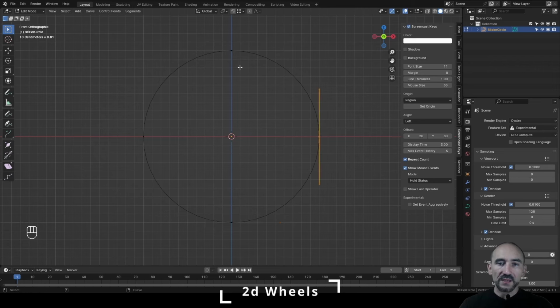Keep in mind these are the control points, so the wheels we want to have inside our tank track. So in this case I will subdivide these segments with the right button, subdivide like this, and I will move these on the Z-axis a little bit like this.